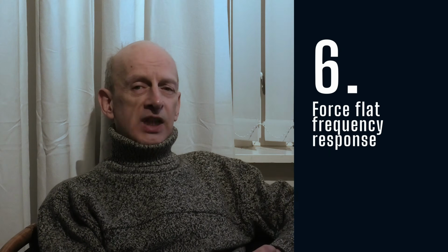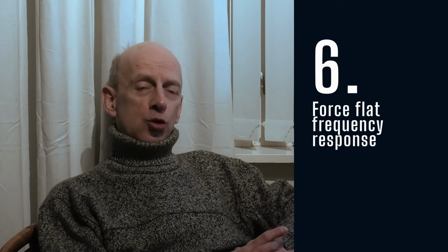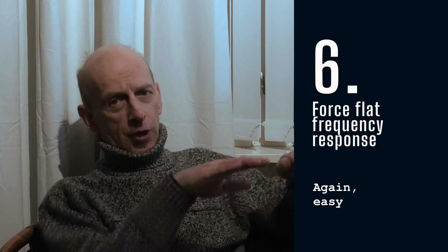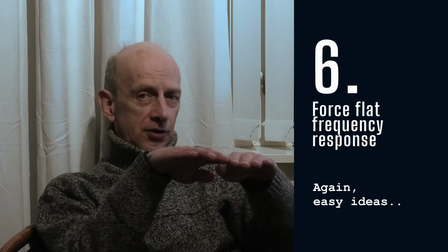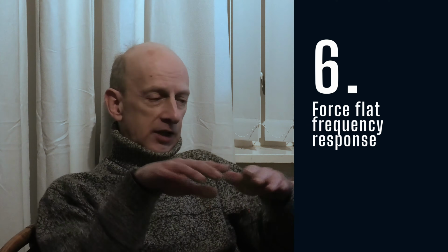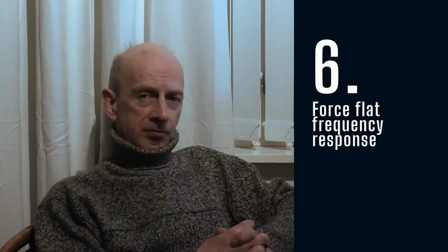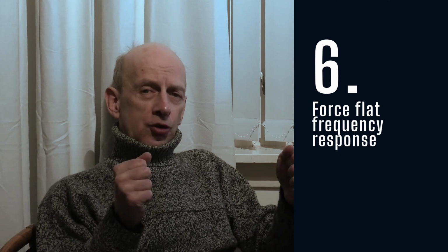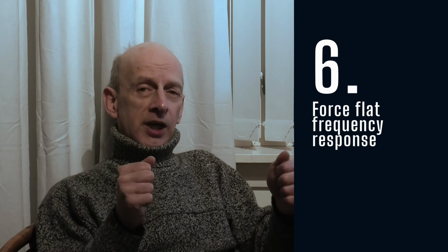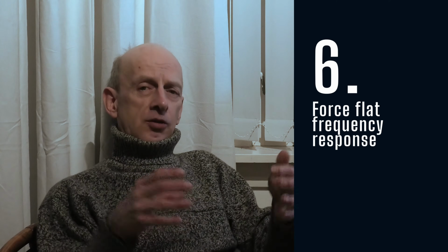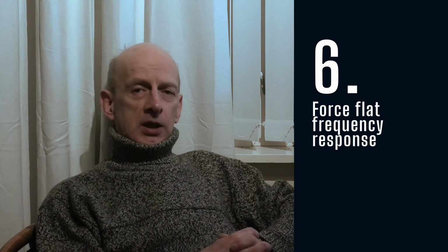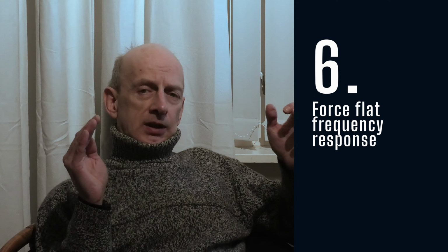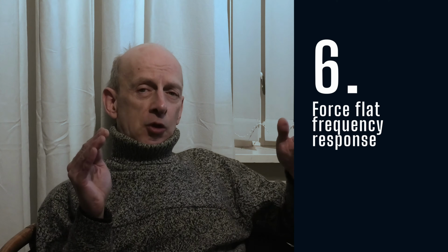Number 6, trying to equalize the frequency response to completely flat, thinking that it has to look perfectly smooth and flat to sound nice. That is wrong. As I mentioned earlier, we need to focus on what happens in the time domain, because that is where the faults are. And also we may not desire to have a flat frequency response.